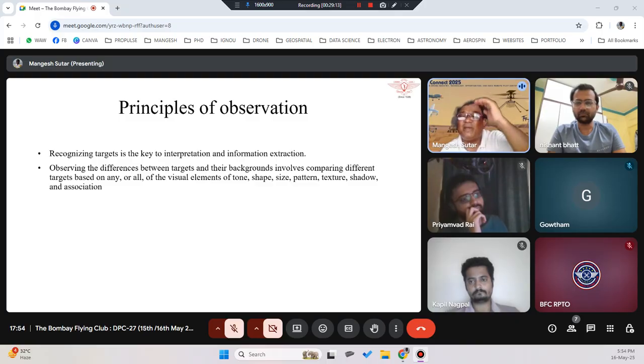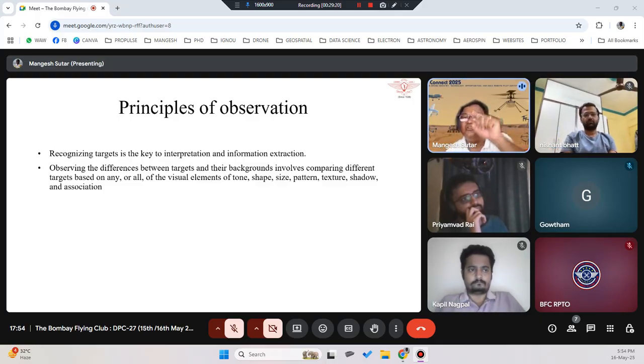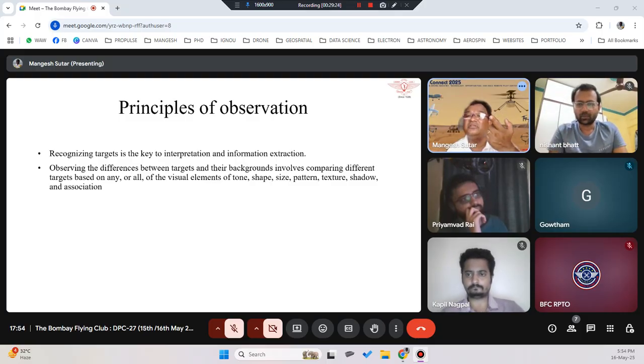Or there are insulator panels on the tower, where the electric wire gets connected. That insulator wire, a lot of times it gets broken because of sparks. It gets damaged, and a lot of times it gets oxidized. All those things have happened, so you need to capture those images. Once we equipped them with that information, they knew what to do. The next time they tried to capture, there was an improvement in their image capturing. But again, that was manual.